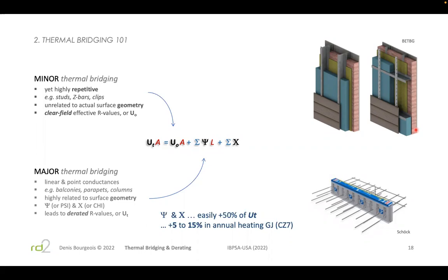This would usually vary for climate zone 7 between 5 to 15%. It really depends if it's an internal load dominated building, a light industrial facility, maybe a call center that operates continuously, versus something like a school or a heated warehouse or a multi-unit residential building. So the range is not negligible, but the impact is noticeable.